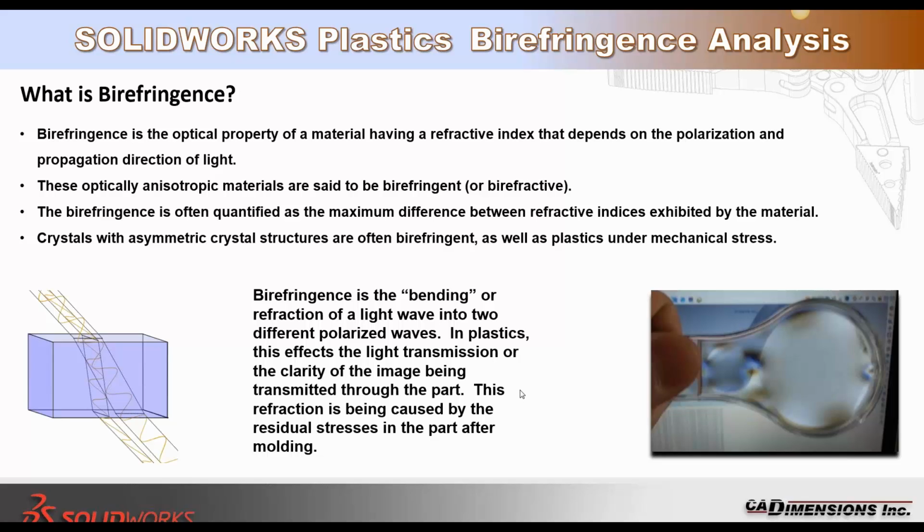And typically this birefringence is caused by the residual stresses in the part after molding. Now, what's nice about SolidWorks Plastics is that you'll be able to see how birefringence is being created within your part at different stages in the injection molding process.